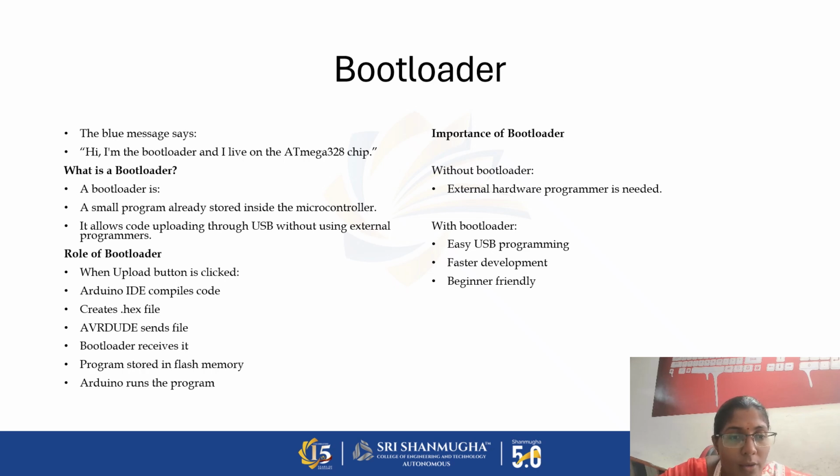What is the role of the bootloader? When the upload button is clicked, Arduino IDE compiles the code and creates a hex file, and AVRDude sends the file. Then the bootloader receives it, the program is stored in the flash memory, and then Arduino runs the program. These are all the roles of the bootloader. Without the bootloader, the Arduino UNO cannot receive the program.